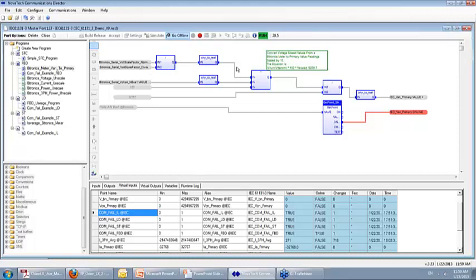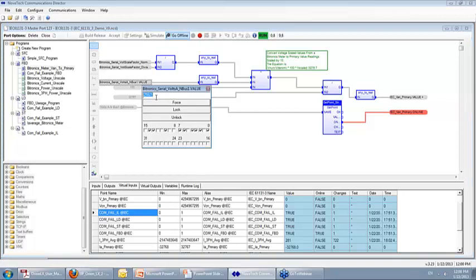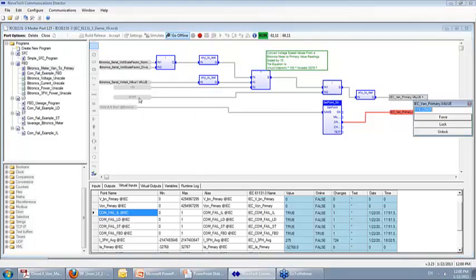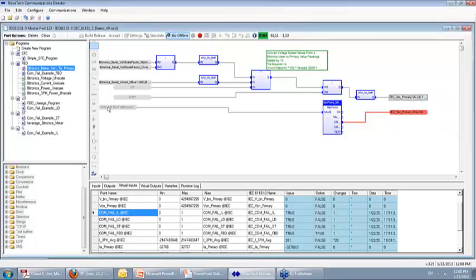I'm taking my scale factor, dividing it, converting it to real, multiplying it by the equation's conversion factors, and I'm reading the real-time value, which in this case is 25,821. I can force those elements in real time to test my logic, but I'm reading them real time. I am dividing them by a constant of 32,767, and I'm coming up with a number, 118.225, for my voltage.